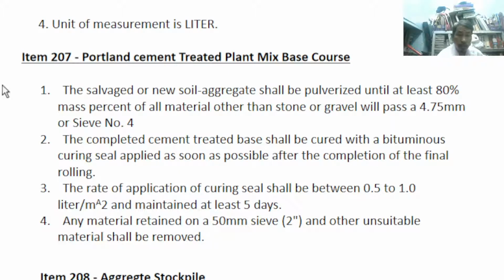Number 1, salvage or new soil aggregate shall be pulverized until at least 80% mass percent of all material other than stone or gravel will pass the 4.75 mm or number 4 sieve. Okay, it should be pulverized.